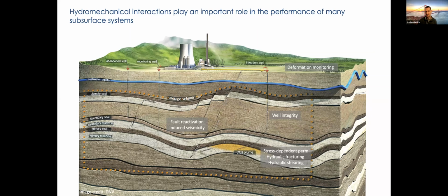And the concern is that changing effective stress conditions in the subsurface could, for example, change the normal effective tractions acting on faults and allow them to reactivate either quasi-statically or potentially rupturing dynamically and releasing earthquakes and seismic energy.